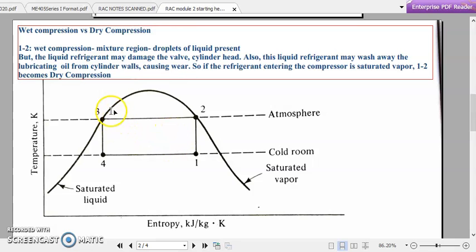In the just previous session, we considered how to represent a TS diagram for a refrigeration system when we were using a working fluid such as a refrigerant, which will be boiling or evaporating during the refrigeration process, that is during Part 2, and which will be condensing during the heat rejection process at the condenser. So this will be the TS diagram for such a system.